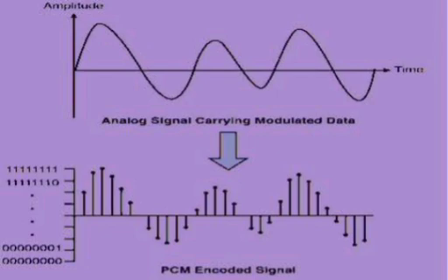Frequency shift keying. The frequency of the carrier is varied in accordance with digital data 1 or 0. For digital data 1, we use frequency F1. For digital data 0, we use frequency F2. Normally, F1 is greater than F2. NRZ signaling is used. Bandwidth requirement in case of FSK is bandwidth equal to 2 RB plus F1 minus F2. In case of FSK, PE is less and SNR is high. Multiplexing is difficult, used in modems.